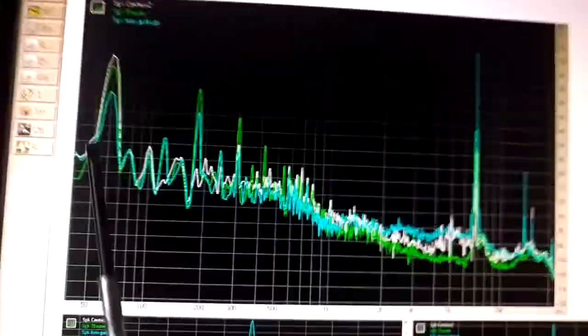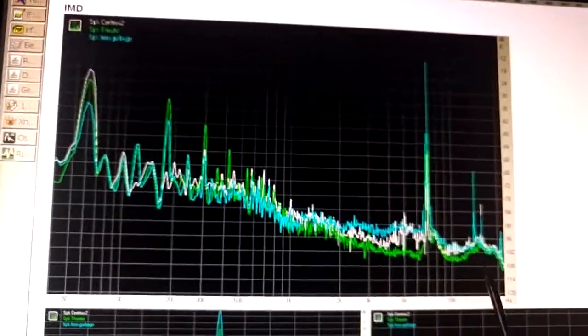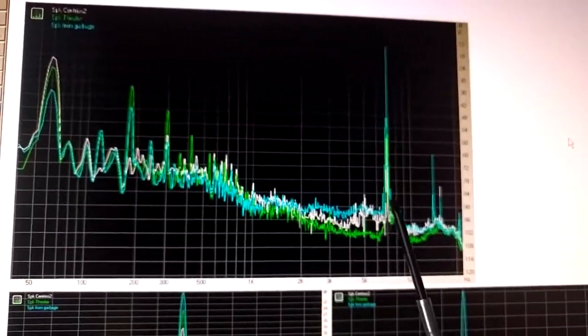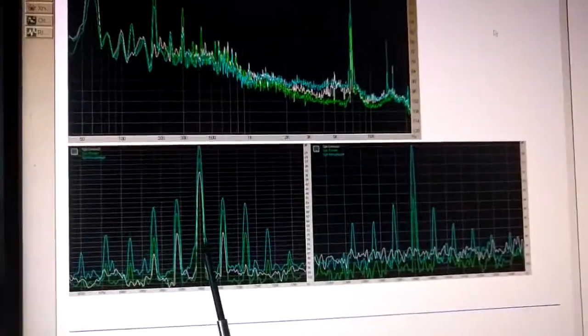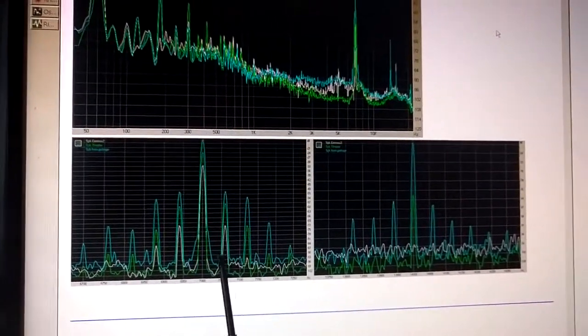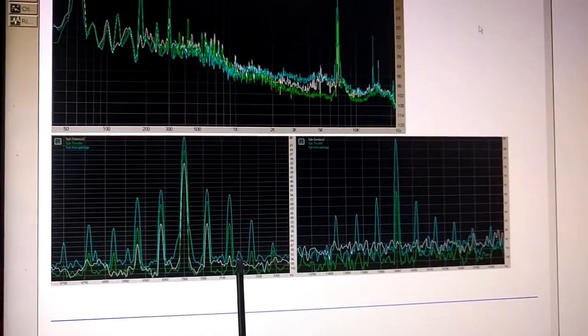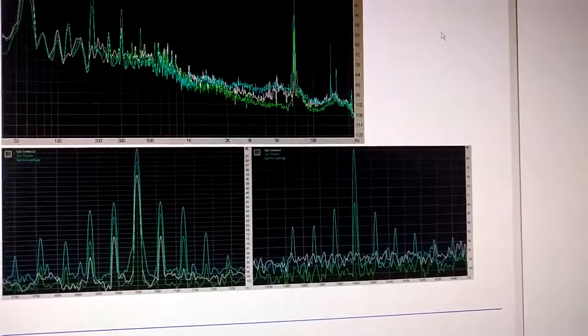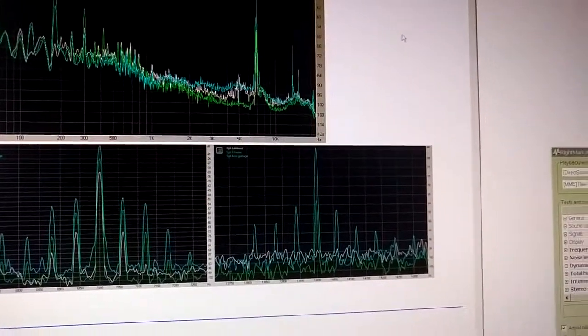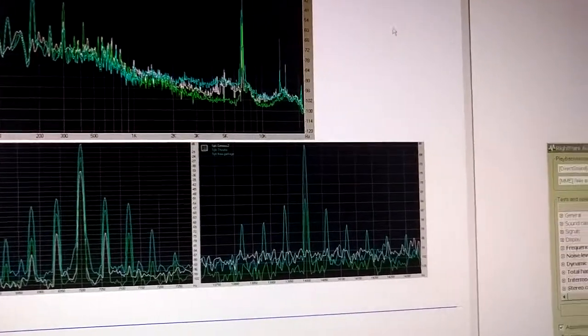If I submit two frequencies, 60 Hz and 7 kHz, I'm going to see the intermodulation of 7 kHz, so it's 7 kHz plus minus 60 Hz, as I described in my previous video. But even with this type of intermodulation, it's still pretty small, minus 6 dB.